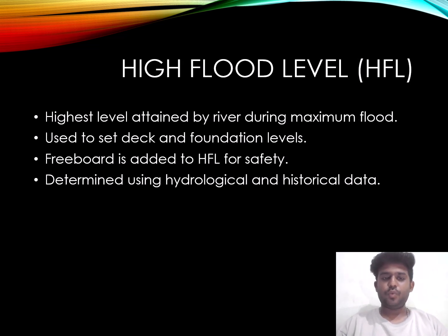Next is HFL, which means high flood level. The highest level attained by a river during maximum flood. This is known as high flood level. Used to set deck and foundation level. Freeboard is added to high flood level, HFL, for safety, determined using hydrological and historical data.